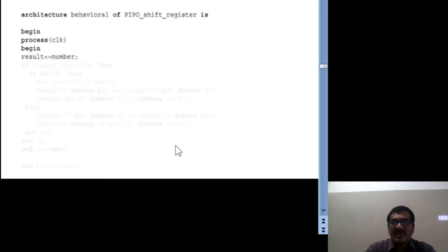So after that I am checking whether a proper clock signal, or proper clock instant, is available or not. It is confined to the positive edge triggering model. That's why, if it is the rising edge of the clock, then only the operations, either multiplication or division, can be performed, otherwise not. So for that purpose we check where the clock instant is, whether at the rising edge, the negative edge, or some other place.